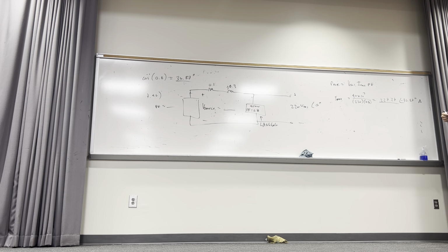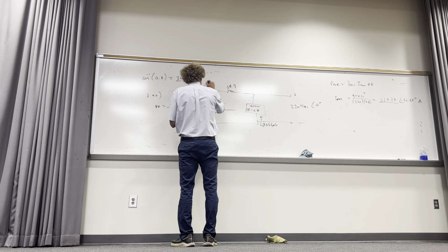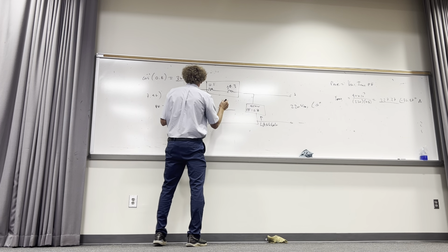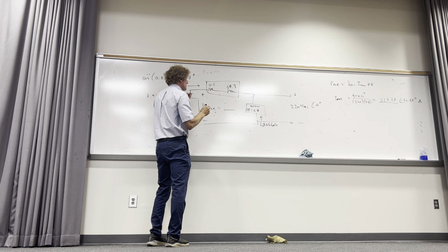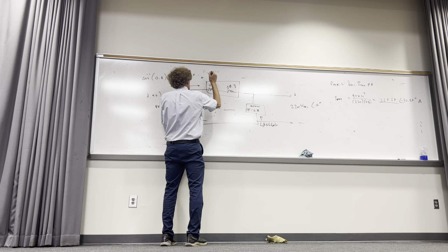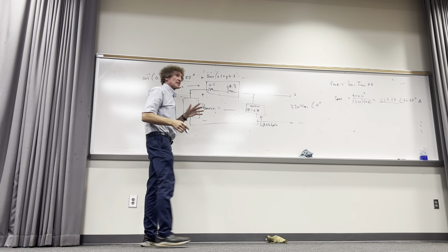All right, not done yet. How do I get the source voltage, magnitude and angle? We covered this. I know a lot of you know, you just don't want to say it. Well, what do I really need? If you look, this is just a line impedance, right? I've got the current now, so that means I have this voltage, plus to minus here, don't I? That would be I_RMS times this, 0.1 plus j0.3. Do you all agree with that?